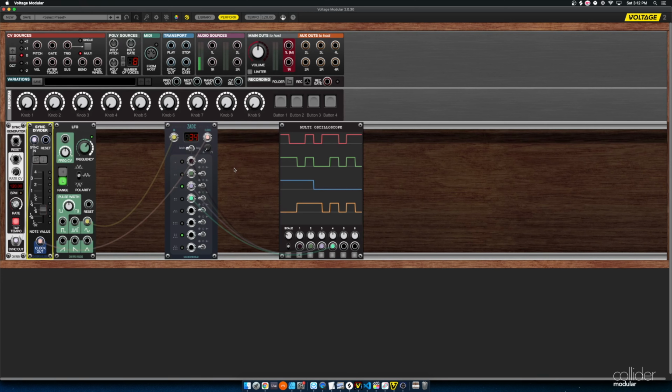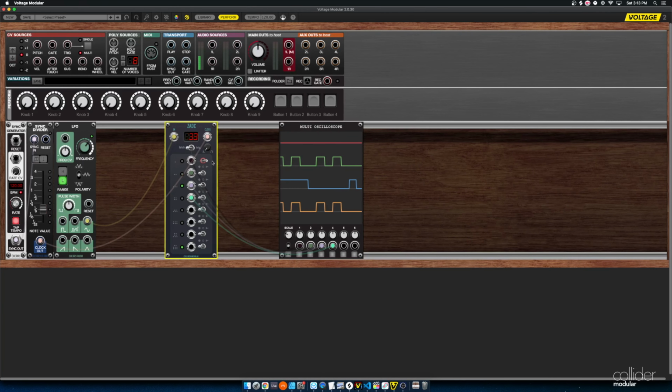There's a couple of other things, and then I'll wrap up this video because this is a very easy to use module, and that is this switch here. So for each output channel or each output bit, there is a 3-way toggle switch that will change the behavior of that channel. So when it is off to the left, in other words, when we have this solid circle, it will be running in normal mode, which is what you've been seeing. In the middle position, it will be muted. There will be no output, so you can see up here on the top, we're not getting any output. And then on the far right, it will be inverted. We will get the opposite of what we were getting.